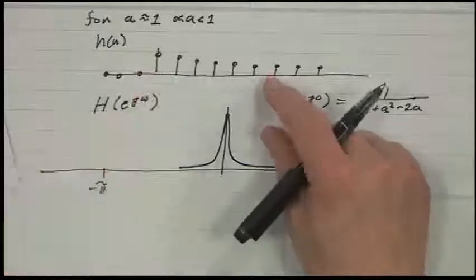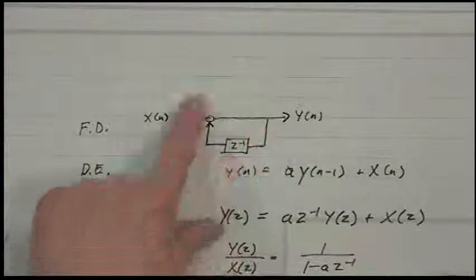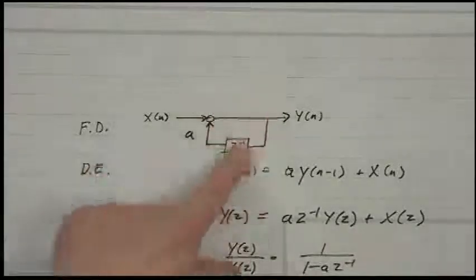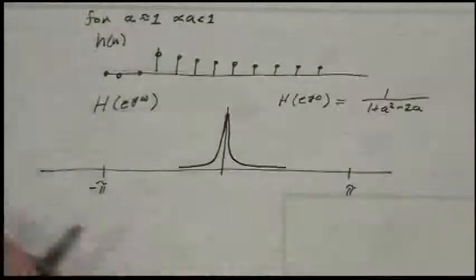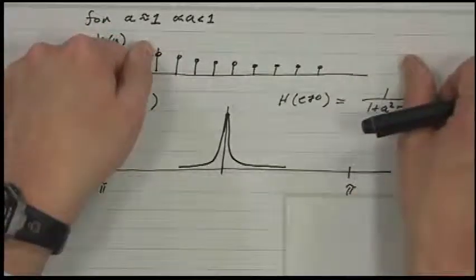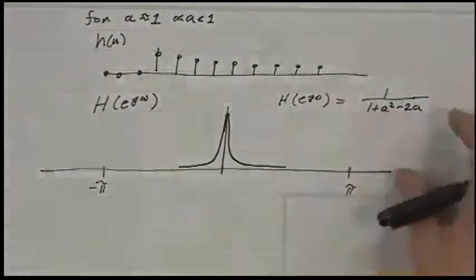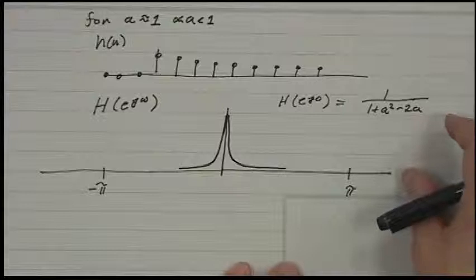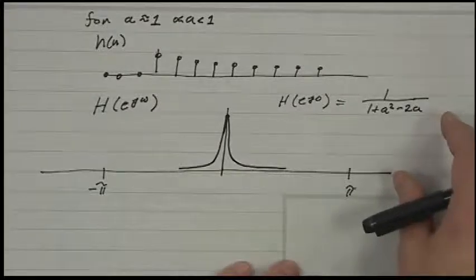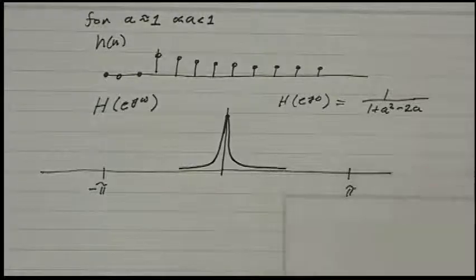So right now, I can implement this filter with 1 multiply per pixel, or 1 multiply per time point. But if I implemented this as an FIR filter, it could be 1,000 multiplies per pixel. So this is something very fundamental. One thing it teaches you is that in signal processing, sometimes there are 2 methods that are equivalent, but one can be implemented with very low complexity, and the other with very high complexity, okay?